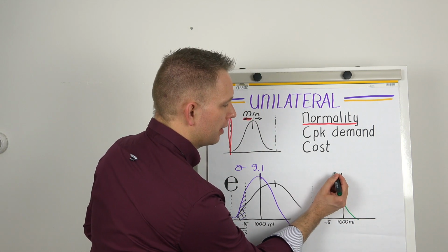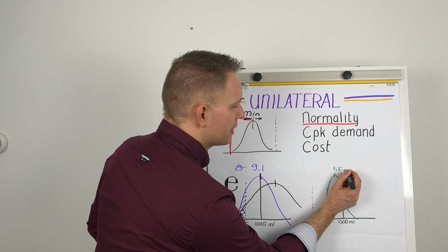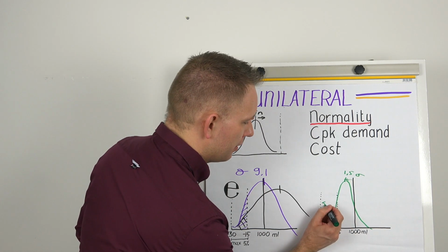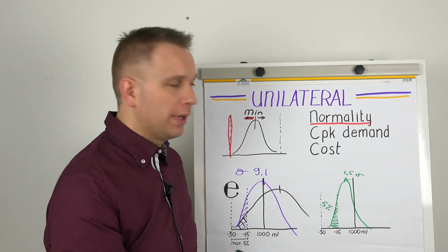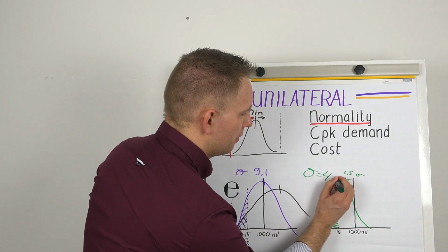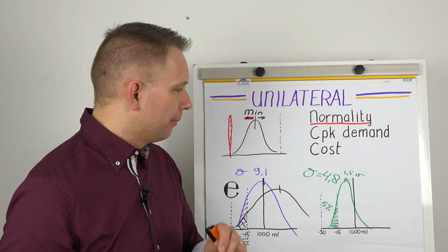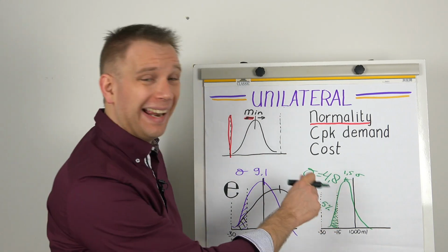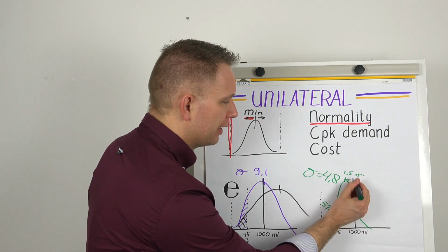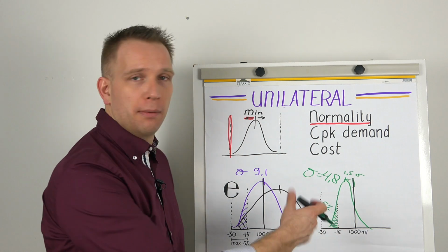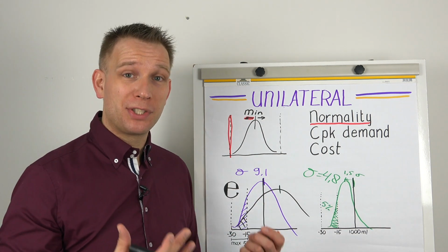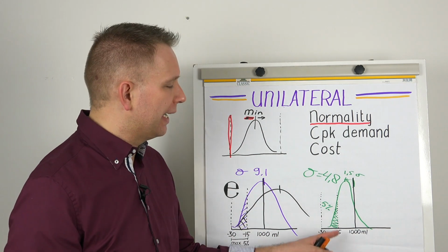We will be 1.5 sigmas to the left, and still this is only 5%. And we get that with a sigma of 4.8. Now, that basically tells us, of course, we are not allowed to produce the whole batch to the left here. Remember, the whole batch should always still be centered, but this allows us a half hour in our shift to produce a little bit less before our systems see it and we correct everything to have a higher weight again.